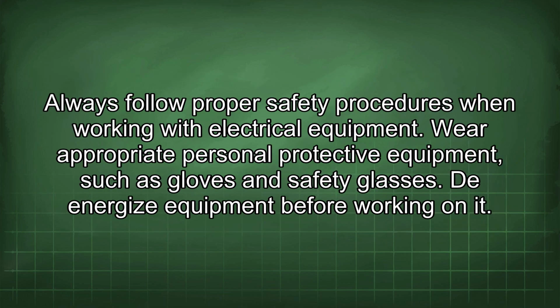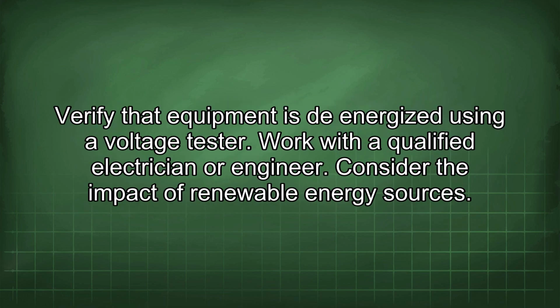Always follow proper safety procedures when working with electrical equipment. Wear appropriate personal protective equipment, such as gloves and safety glasses. De-energize equipment before working on it. Verify that equipment is de-energized using a voltage tester. Work with a qualified electrician or engineer.